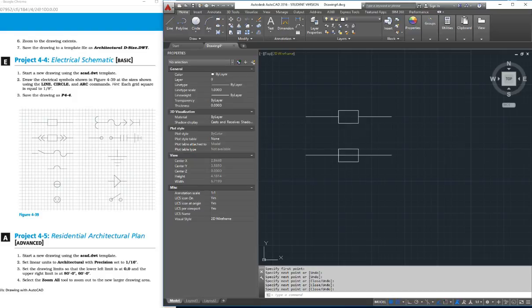You could either use this tool here, trim, and underneath it there's one to make things longer. Trim makes it shorter, extend makes it longer. So what I suggest, once you have this, you just type TR, trim. Now here's the trick, enter, enter. And then just pick the line you want to go away. And that'll go away in there.